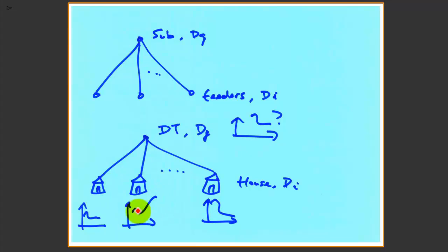So what we have to do is a load survey to get snapshots of data from each household, and then we lump them together for each distribution transformer, or it could be the same thing for each substation feeder head corresponding to each FRTU. So this is the kind of study that we have been doing a lot.